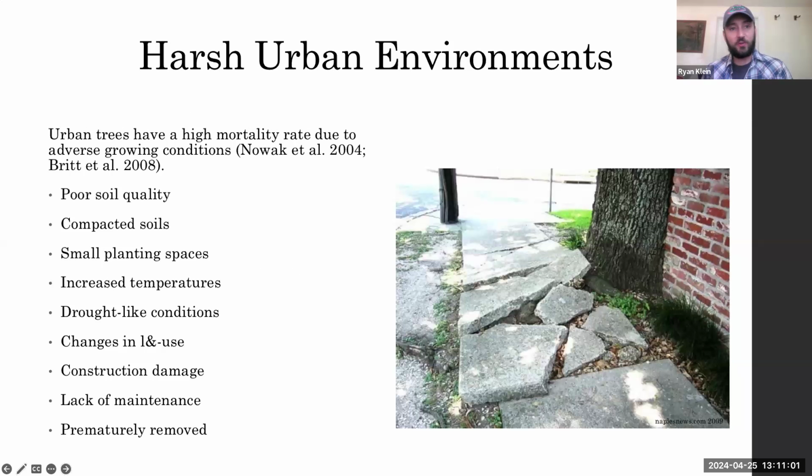So that, coupled with the already harsh conditions that trees grow in these urban areas, typically trees are going to grow poorly in the urban landscape if infrastructure is not developed to accommodate future root growth. So think of it as, that 3-inch tree works in that little 4-foot wide planting strip when it's planted, but then, over 4, 5, 10 years starts to outgrow that space. And as that tree becomes middle-aged and makes its way to maturity, it's definitely outgrown the space, damages infrastructure. A lot of times when they replace the infrastructure, the tree's damaged. It's a vicious cycle. So we got to do better with designing for long-term performance.